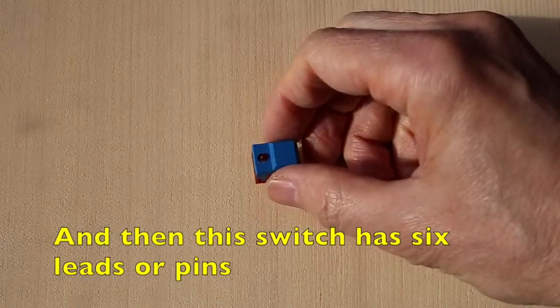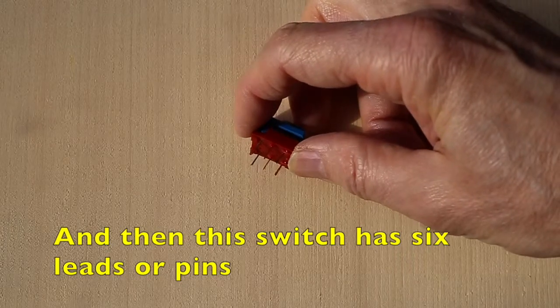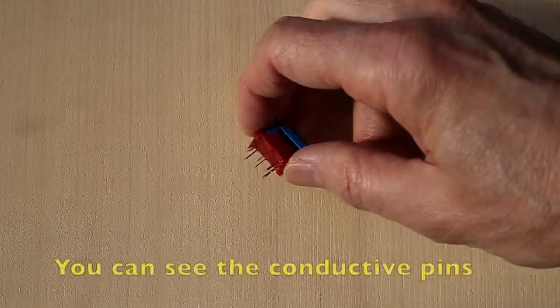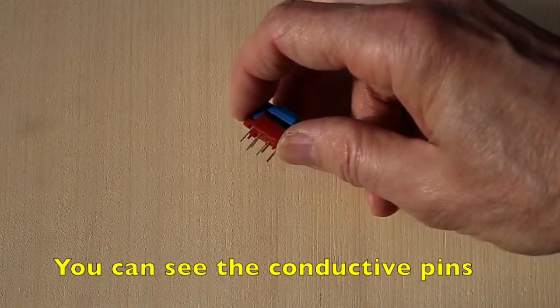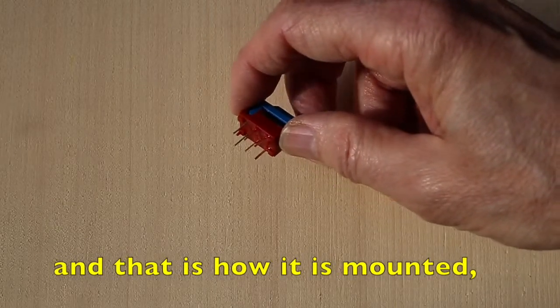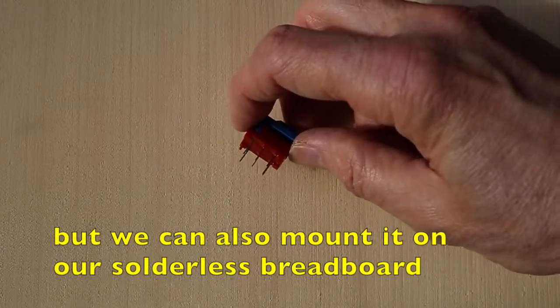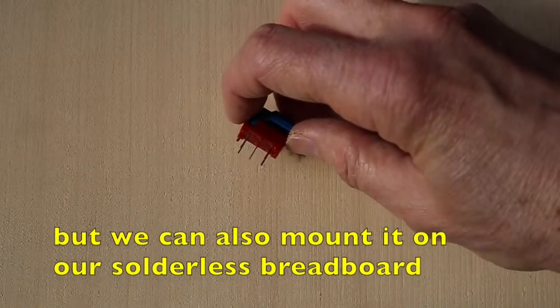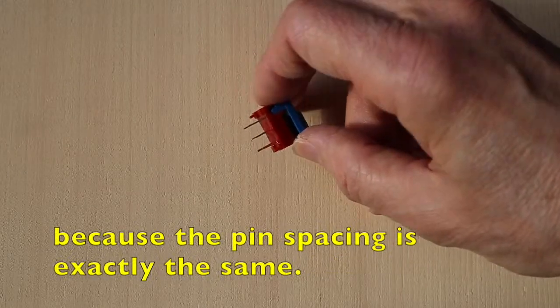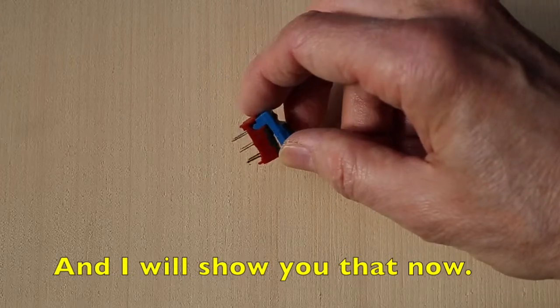And then this switch has 6 leads or pins. You can see the conductive pins, and that's how it is mounted, intended for a printed circuit board. But we can also mount it on our solderless breadboard because the pin spacing is exactly the same, and I will show you that now.